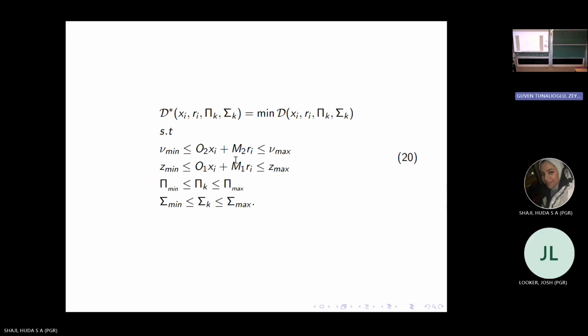Because we did all this work, we can write the constraint here for the mean input and mean state in this form. So here, with a little bit of simplification, we can write everything in terms of R. And then we can apply the constrained optimization problem. And since it's quadratic, we can follow the active set method. The active set method we can solve numerically, typically in MATLAB.